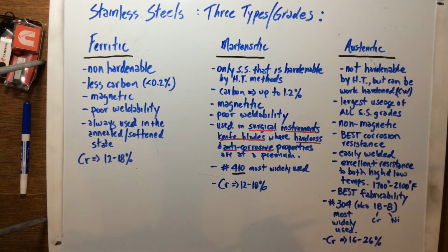And for the most part, all stainless steels have fairly low carbon content, usually no greater than 1%, but they can get a little higher, especially obviously on this one. But generally speaking, they have fairly low carbon contents. Where the properties come into effect are with the alloying of specifically chromium and also nickel. When combined, that's where stainless steels really get their enhancements property-wise, mechanical property-wise.